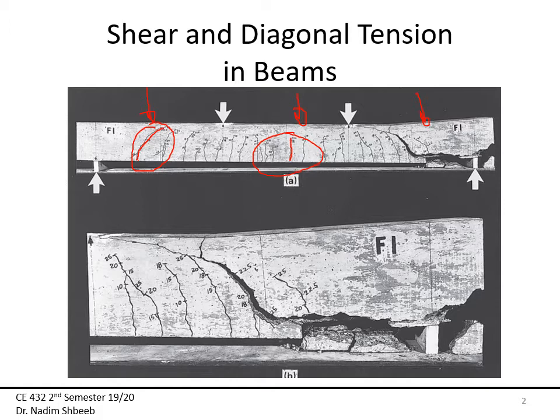One of the things that we actually emphasize is why do we need shear reinforcement? Well, in flexure, we always told you that my primary concern in the design is to ensure that we have yielding in steel so that we can have a ductile failure. So if I have a ductile failure, then I have time to actually do some maintenance, maybe warn the occupants.